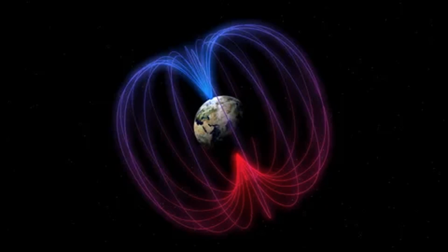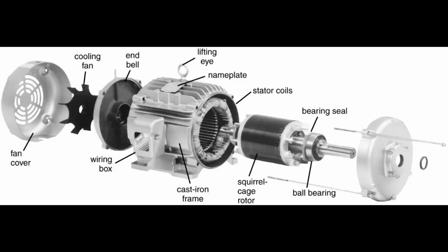In summary, voltage regulation in an alternator is managed by a voltage regulator that adjusts the field current to maintain a consistent and appropriate output voltage. This ensures that the electrical systems receive stable power and the battery is charged optimally, enhancing the overall reliability and performance of the vehicle's electrical components.